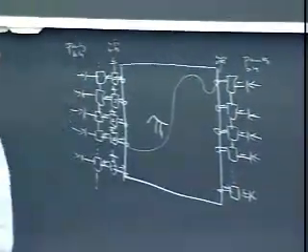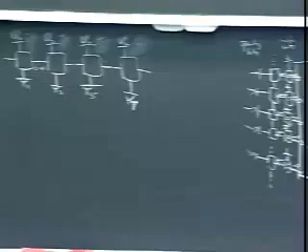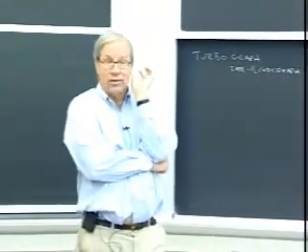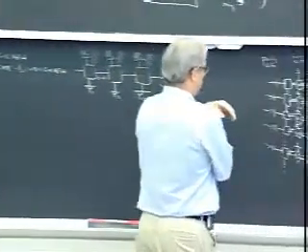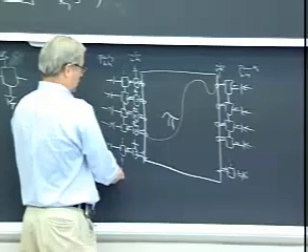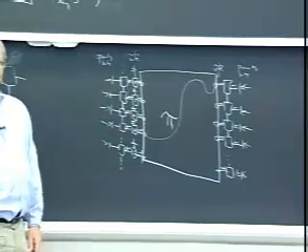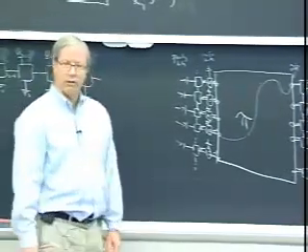Okay, somebody else. What's the next step? Somebody was just about to say it. Be bold, somebody. Convolutional. Excuse me? The trellis decoding. Trellis decoding, right. If we forget about that side and just look at what the sum product algorithm does over here, we're doing the sum product algorithm on a trellis, the BCJR algorithm.